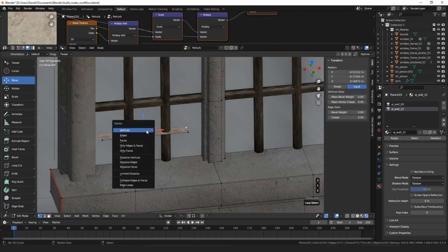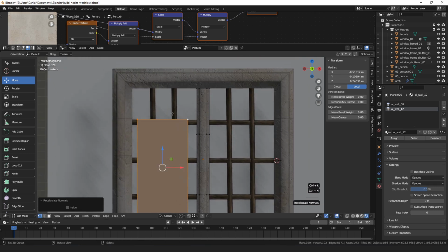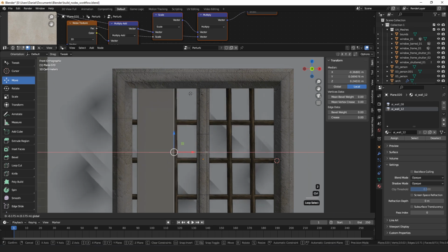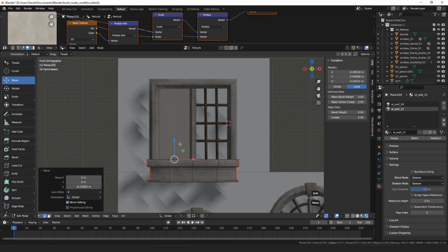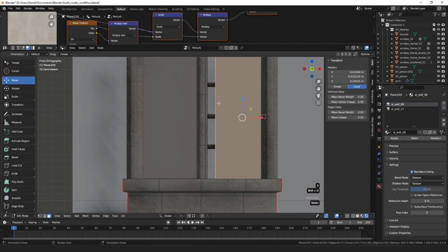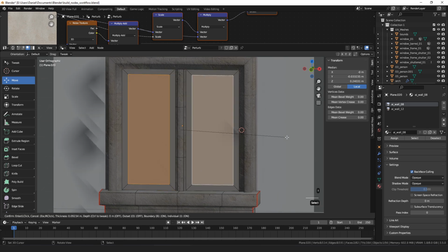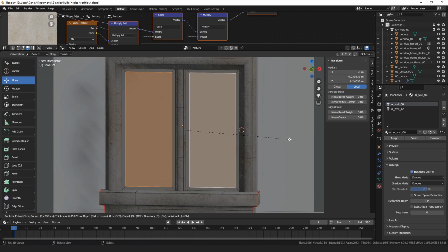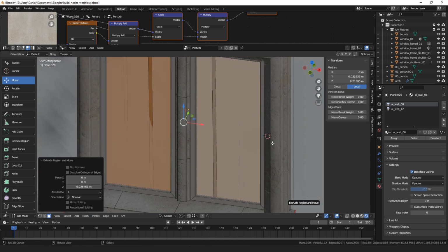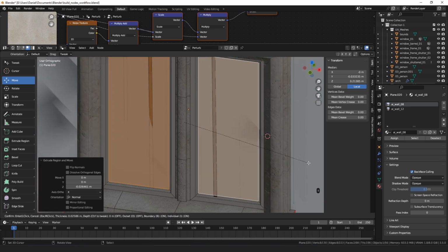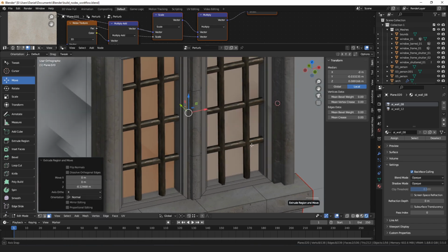So I'm actually going to make a plane. Flip to normal. We're just gonna line it up so that it fills the space. And then we can make a copy of it. And they should be the same size. What I'm going to do is inset them some amount, and then we can just extrude back a little bit. And then we can inset them again, just add a little bit of detail, and then extrude all the way through. We'll extrude it further, and then